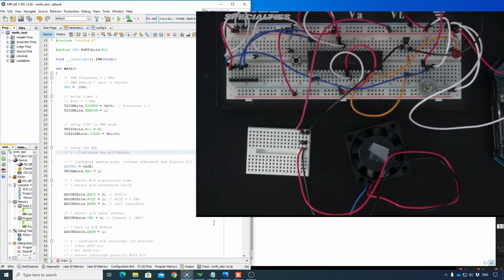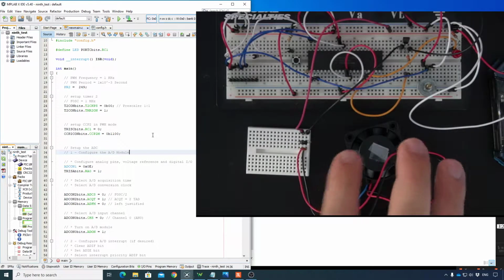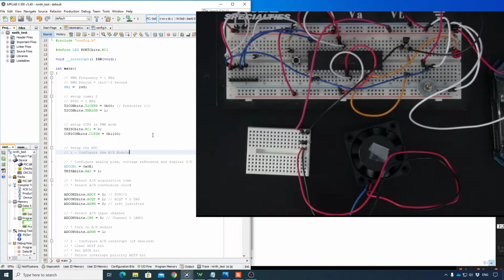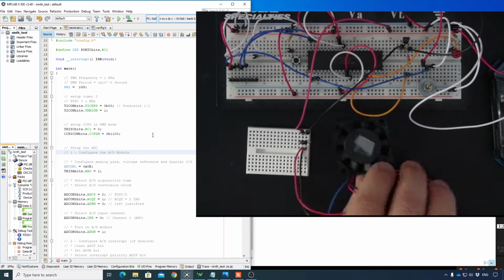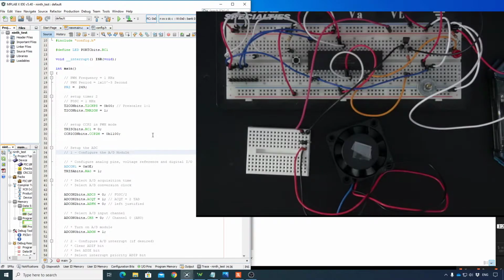Okay, but you're going to see that there are a few ways to connect the motor to my microcontroller. Of course, you can directly control it with the pulse width modulation. However, that's a bad idea because these motors draw a lot of power, and it might draw too much current for your microcontroller to handle, and at that point you will be burning your microcontroller, or maybe ruin it. So what you usually do is you power it from a different power source, and you isolate it from your microcontroller, and the pulse width modulation signal will be the thing that you control the speed with.